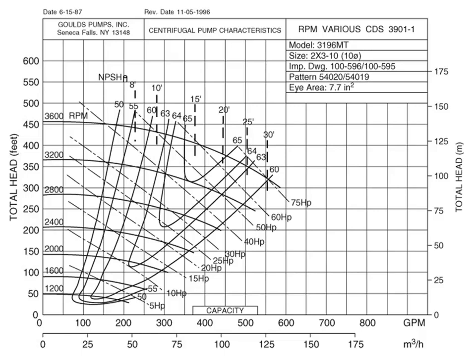Then you may have to flip through several different pumps to find the right combination of head production capacity along with flow rate and the suction head requirements. And then the other aspect of it is finding an operating point that matches the electric motor that you'd like to rotate at. So there's a lot of considerations there.